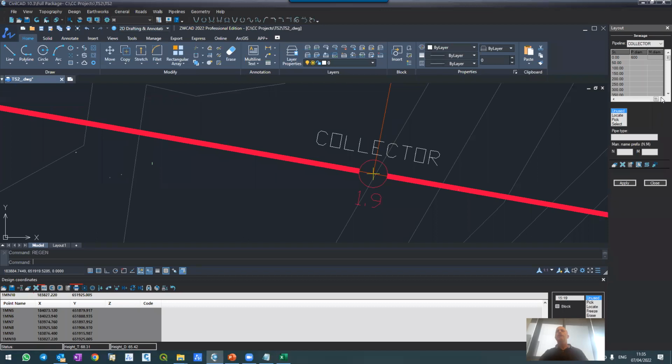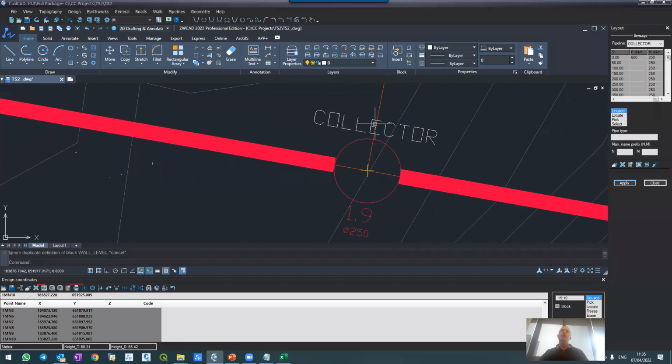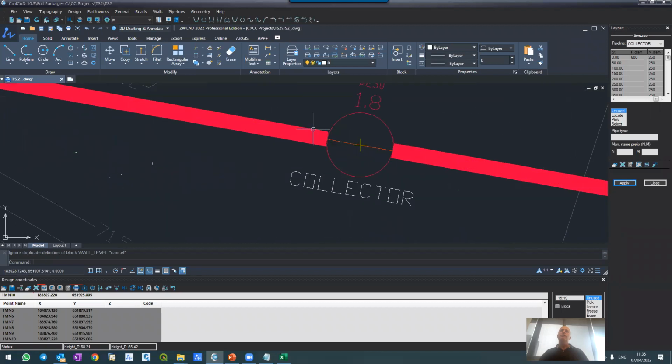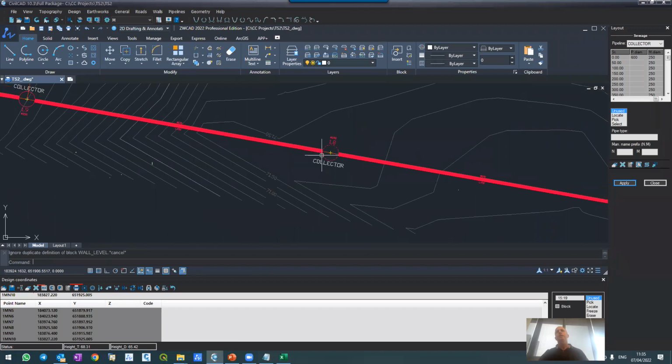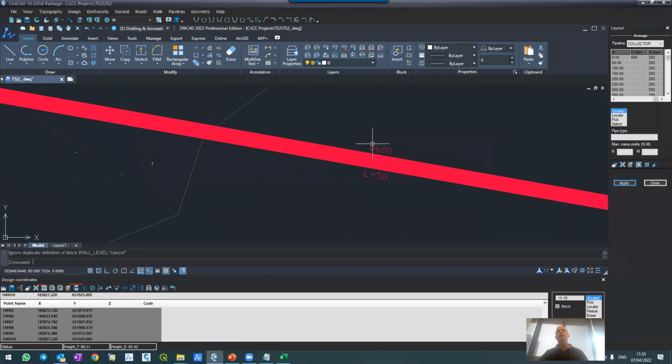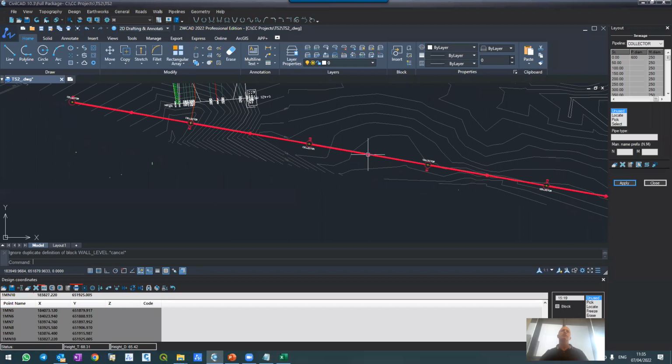And I also want to give size to the manholes. In this case, the manholes are all 250 cm. And I apply. So you see, the manholes become bigger at 250 cm, and the sewage pipe itself is also bigger to reflect 600 millimeter. And the data is here. Also, the data appear here. This is the 600 millimeter and the length between the two manholes, 50 meter.